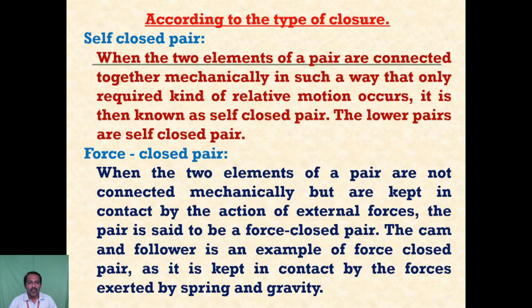Next one is a force-closed pair. When the two elements of the pair are not connected mechanically, but are kept in contact by the action of external force, this pair is called a force-closed pair. A cam and follower is a good example of a force-closed pair.